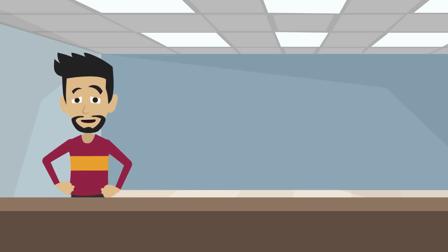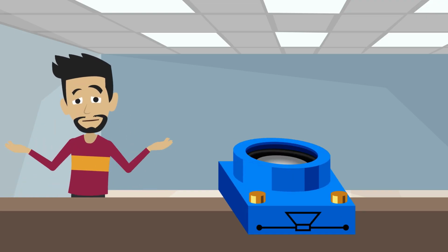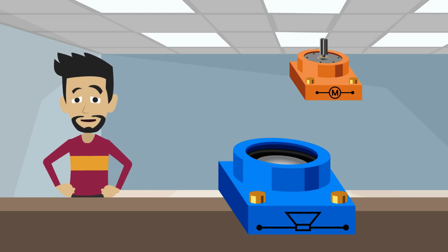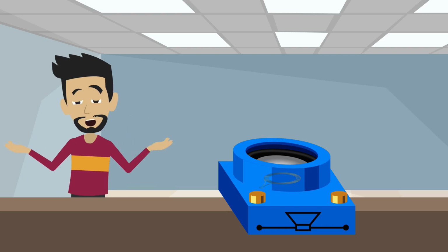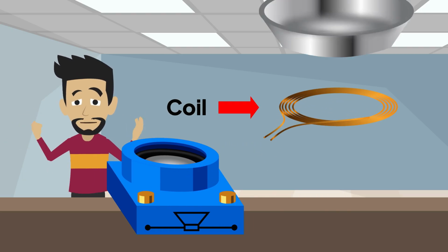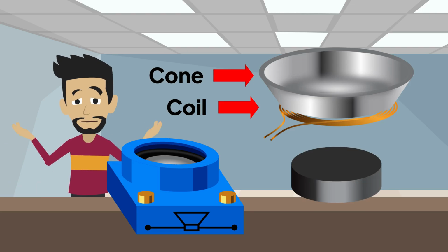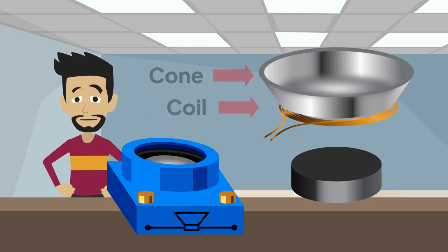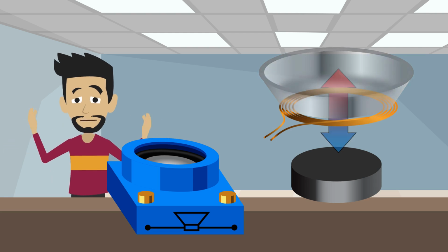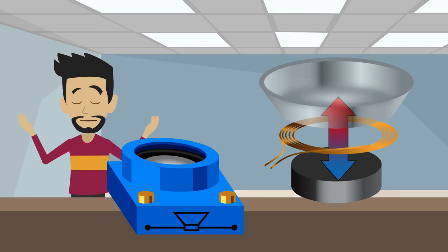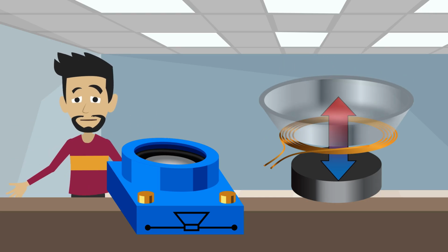So now that we know how sound works, how does a speaker make sound? Well, speakers are actually kind of similar to motors. Inside the speaker is a coil of wire attached to a thin paper or plastic disc called a cone. Behind the coil is a strong magnet. When electricity flows through that coil, any guesses what's going on? Yeah, it's going to create a magnetic field. But this time, instead of spinning like a motor, the coil is just pulled towards the magnet. The attached cone also moves with it, pulling it back into the speaker.